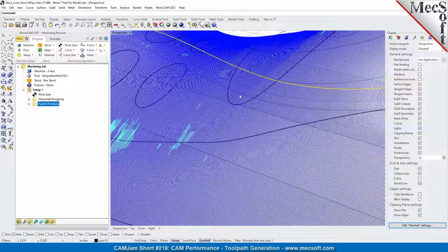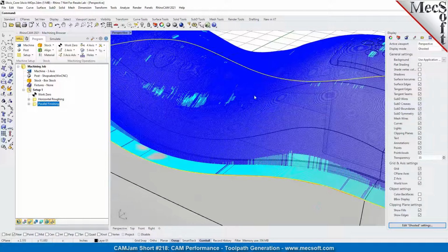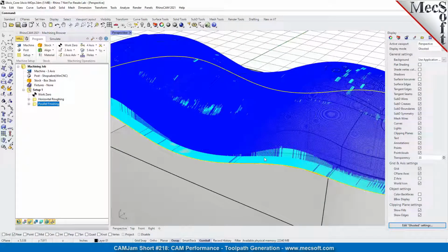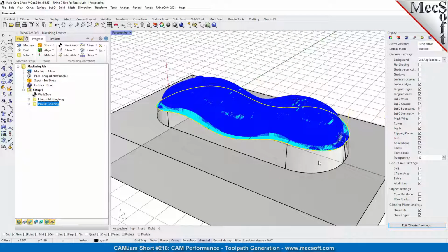So when we do the linearization, the tolerance affects the linearization. And the tighter the tolerance, the more data the CAM system is using in its computation. So it does result in more toolpath points, like what Don is saying, but that's just a side effect. The main effect is it's increasing the data being input into the CAM system.